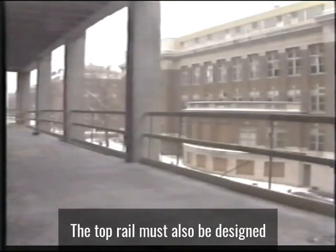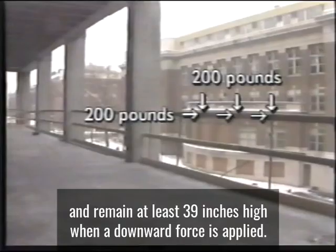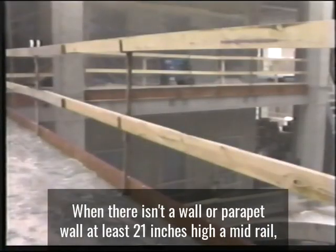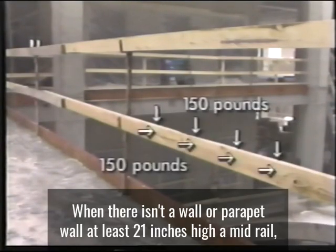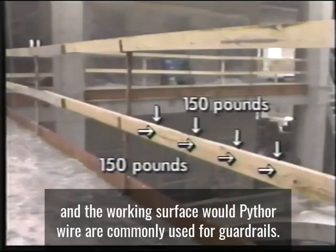The top rail must also be designed and constructed to support, without failure, at least 200 pounds of pressure and remain at least 39 inches high when a downward force is applied. When there isn't a wall or parapet wall at least 21 inches high, a mid-rail, which can support 150 pounds of pressure, must be placed halfway between the top rail and the working surface.